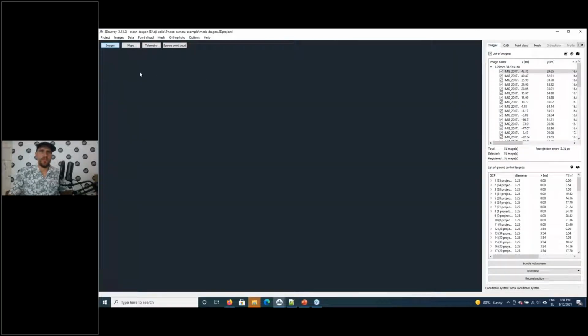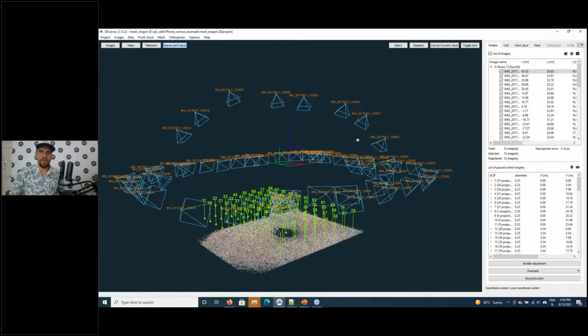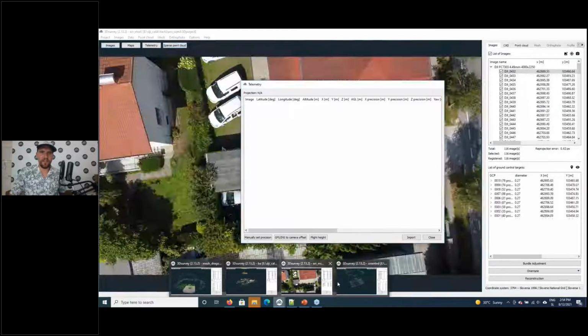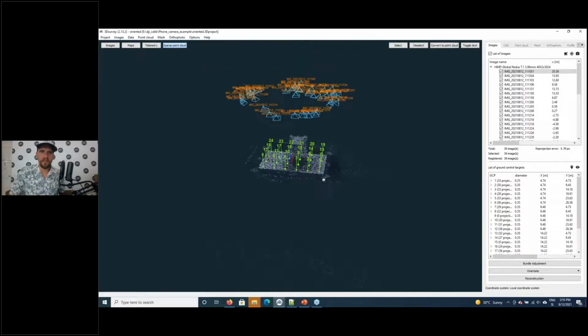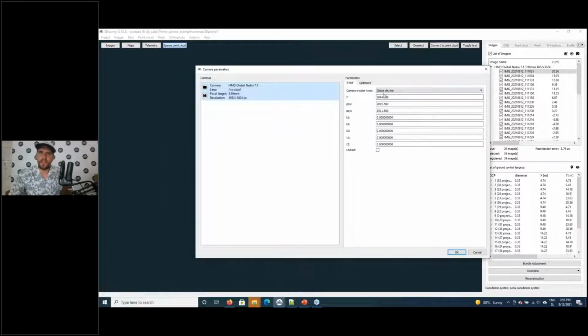One last thing to note is we set in the beginning the focal length will change depending on how far we are from the model. So in this case, if we record from this distance, the focal value will count for this. If we use the same phone to maybe map a building or something big, you would probably expect this value after bundle adjustment to change by some 10, 20, 30 pixels, something like that.